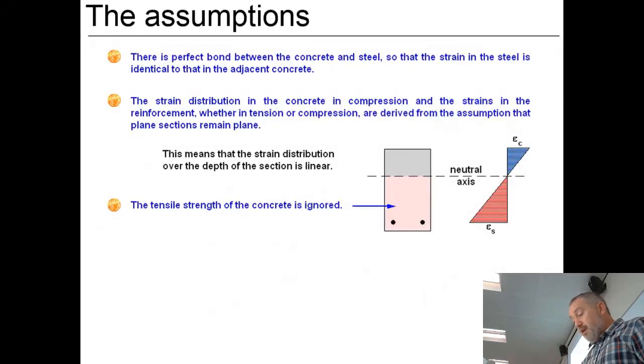So you've got epsilon, and just like what I've said there, this is just saying that the pink area below the neutral axis is concrete, that we don't consider any tensile strength from the concrete.